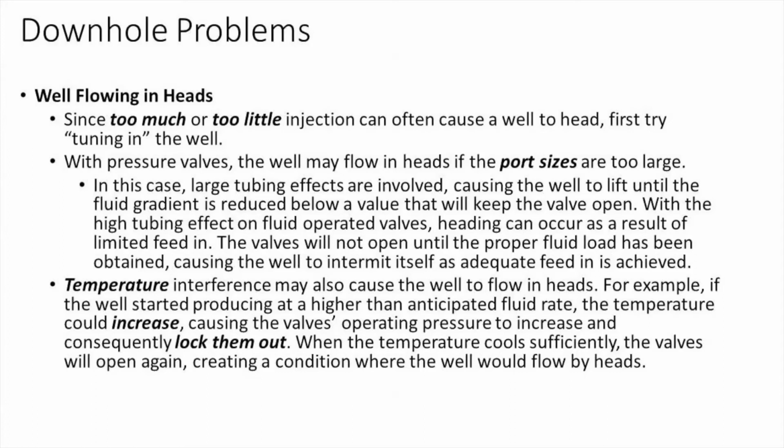Flowing in wellheads, well slugging, very common with horizontals, can also occur through under-injecting or over-injecting in the well. So as we've gone through, a lot of the troubleshooting issues are tied back to optimization. Again, this can be identified through our optimization selection because we could be either over-injecting or under-injecting the amount of gas that we're utilizing for the field.